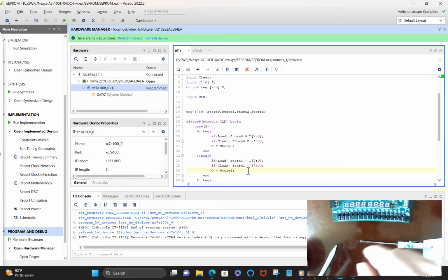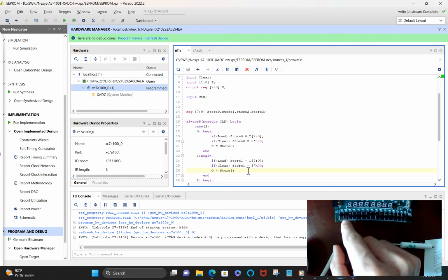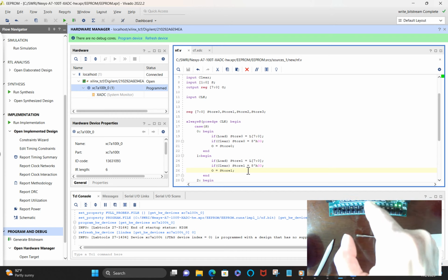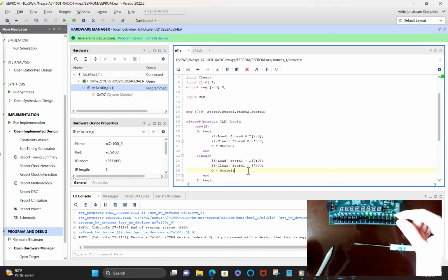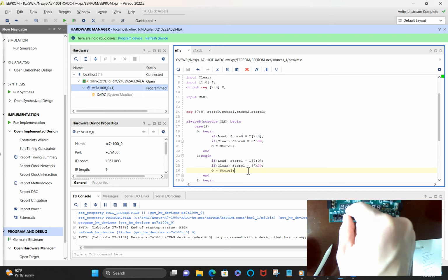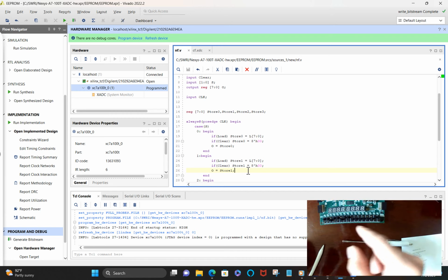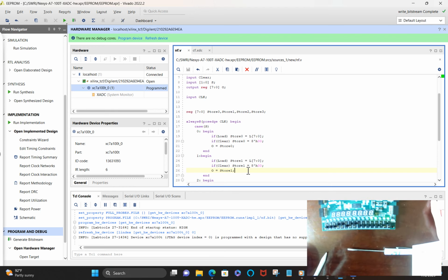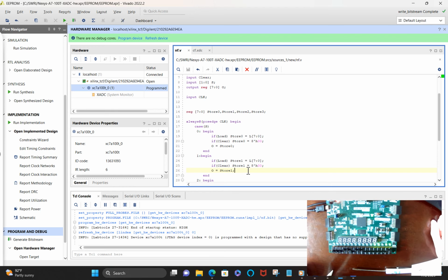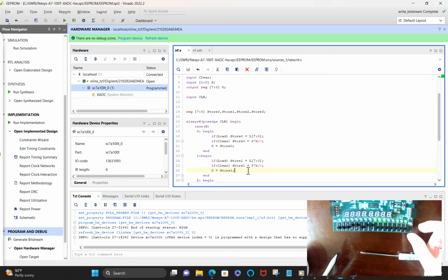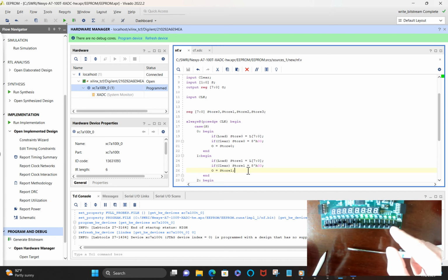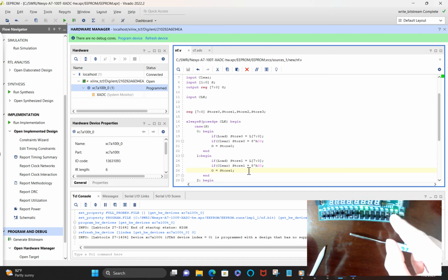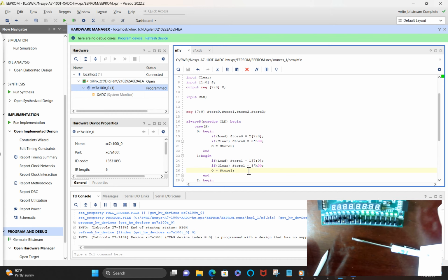Now let's go to 2. Let's load in something else now. Let's load in 11000011, and it reflects that. Go to 11, the last address, and load in another thing. That goes right there. Okay, so go back to state 0. It kept the value we put in. Same thing with 1, same thing with 2, same thing with 3.